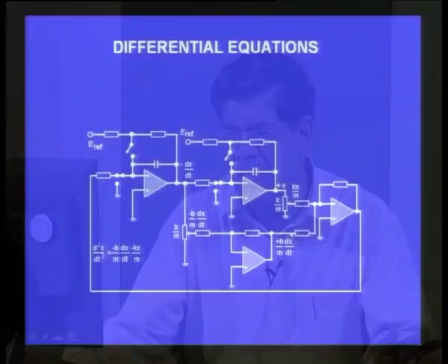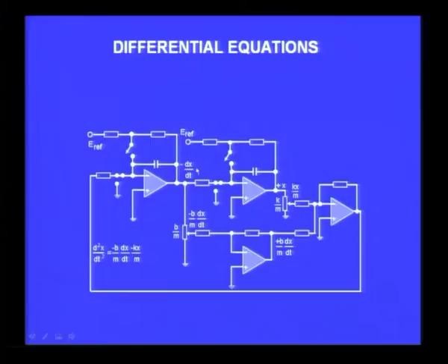with the input and the output conforming to each other, and therefore, you get the complete differential circuit implemented using these op amps, integrators mostly, and one inverter. This is a summing amplifier, this is an inverter, and these two are integrators. The initial condition can be set by using E reference and things like that, and the greatest advantage of this is that you can understand a real situation if you know the corresponding damping factor, the frequency factor, and things like that. You can modify this and try to implement the corresponding system over here and study that very quickly.